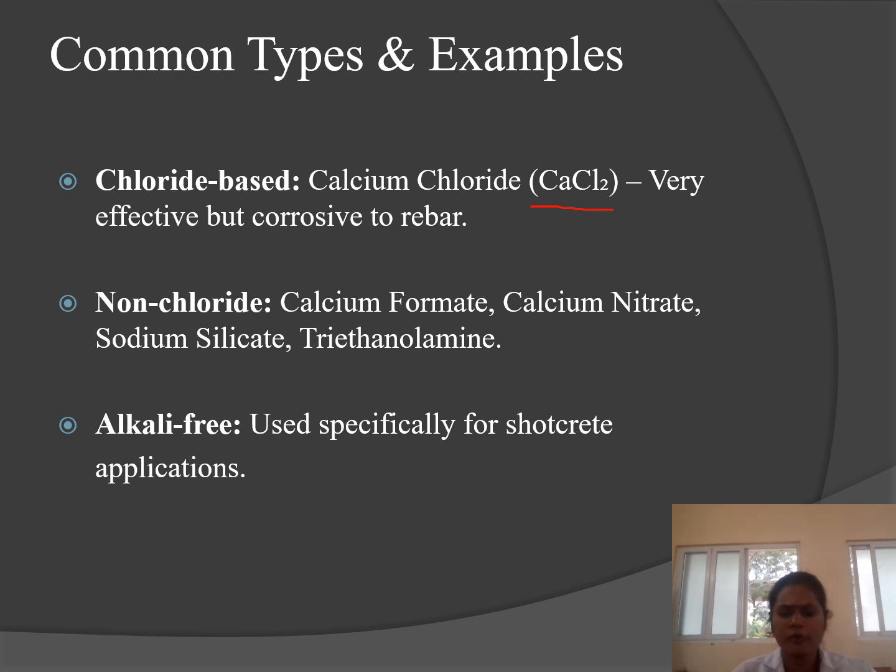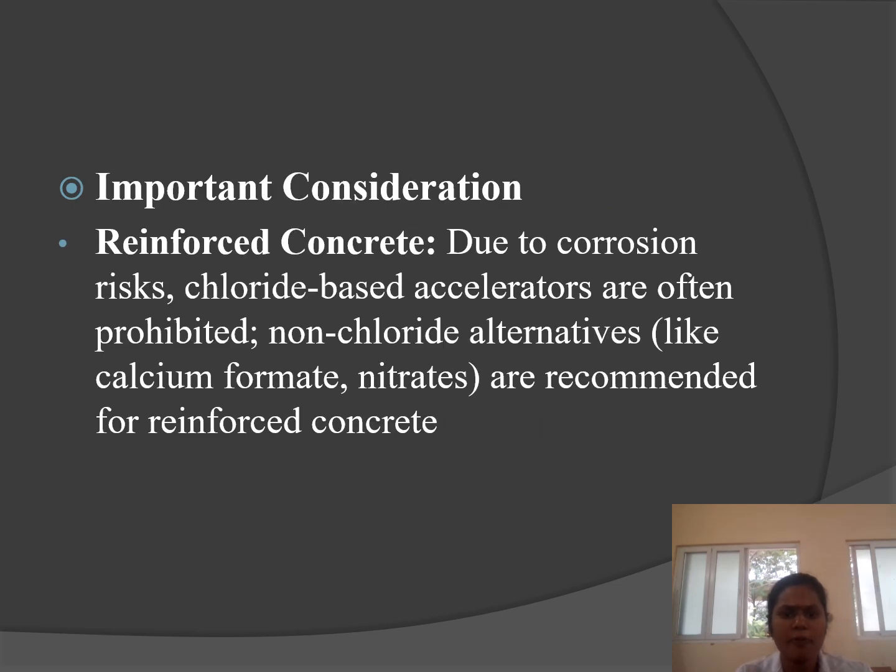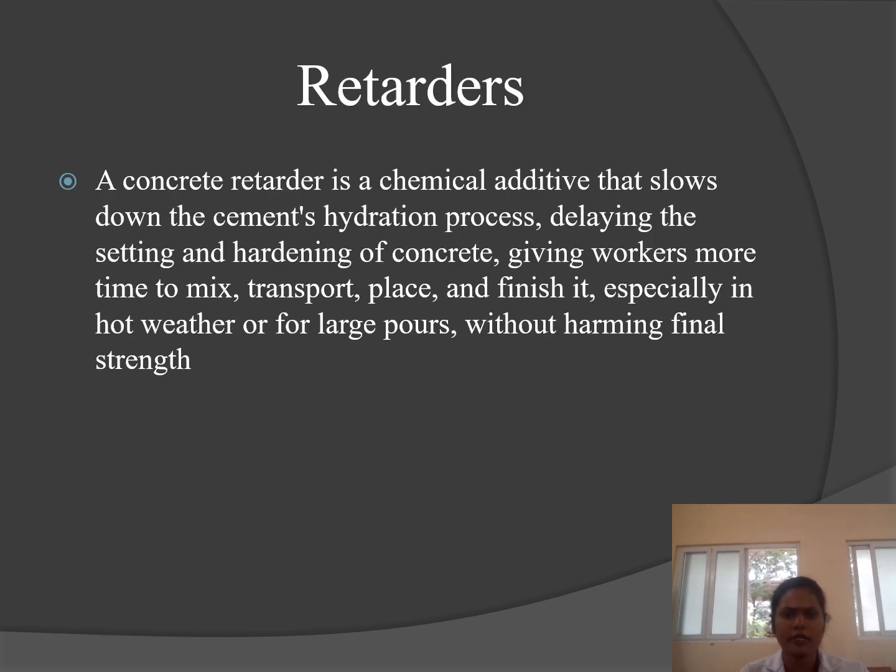Calcium formate, calcium nitrate, sodium silicate, and triethanolamine, used specifically for shotcrete applications. And the next one is an important consideration. For reinforced concrete, due to corrosion risk, chloride based accelerators are often prohibited. Non-chloride alternatives are recommended for reinforced concrete, RCC.